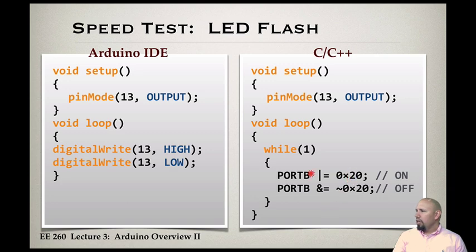If you ignored this while loop, the function would still turn on and turn off, but you would not get a nice duty cycle. It would be on for a very short period of the duty cycle, and then it would be off for more of the time, because it takes longer for that loop function to execute than it does for the while loop to execute. So this is one of those programming tricks that you learn mostly by trial and error, or someone else's trial and error.